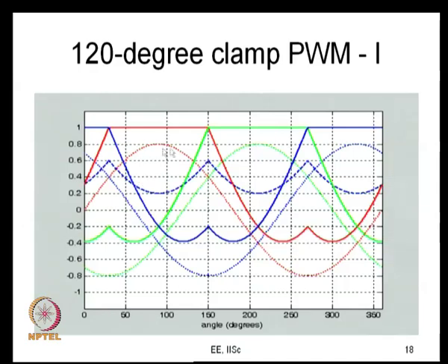So, you can see that the top devices have a higher conduction loss than the bottom devices, and that is what we saw as a disadvantage in doing this. Why is this happening? Well, because you are adding a common mode component whose DC value is not 0. That is what we would consider. So, its DC value is not 0.